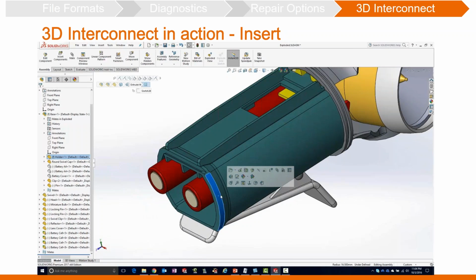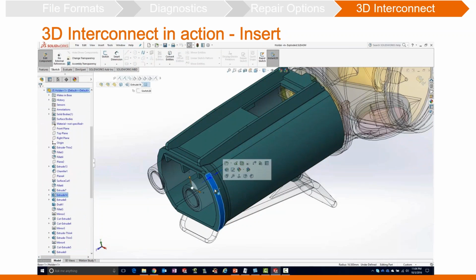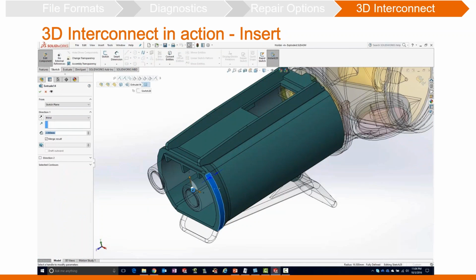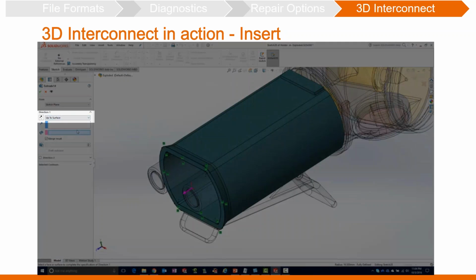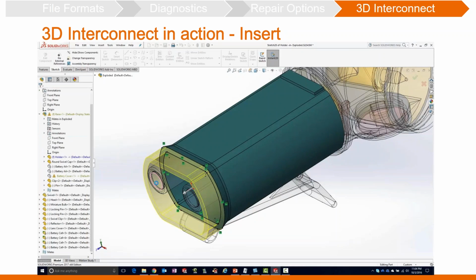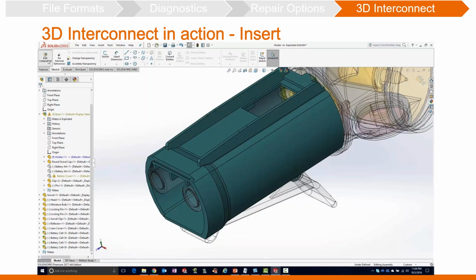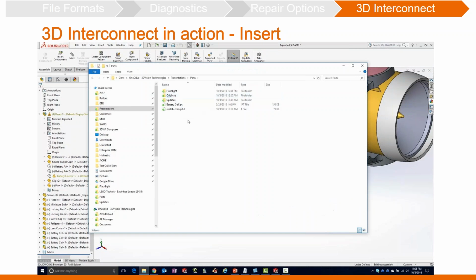We'll slow it back down to normal speed here. And what we want to do is attach this extrusion to one of the faces on the battery. So these are not just geographical representations of the batteries. There are surfaces and faces here that we can choose from, so that the body of the flashlight now can be related back to the geometry of those batteries.